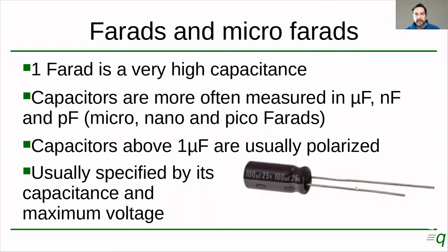I would not go by the length of the terminals, but by what's marked on the case. When you purchase a capacitor, the two main values that you want to specify are the capacitance, in this case 100 microfarads, and 25 volts, which is the maximum voltage that this capacitor can withstand without being damaged.